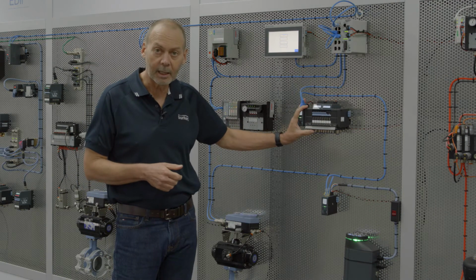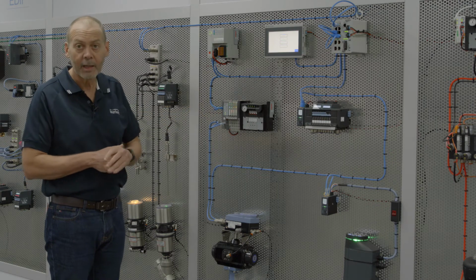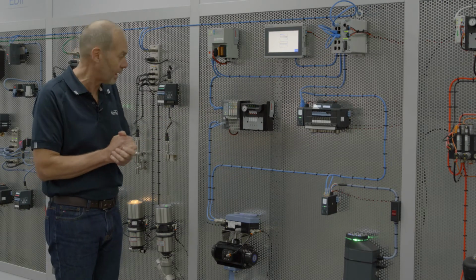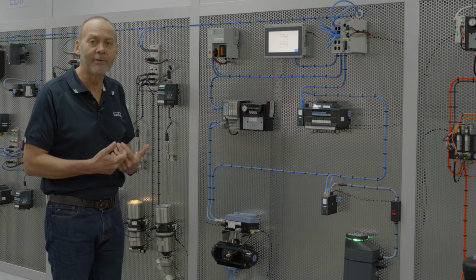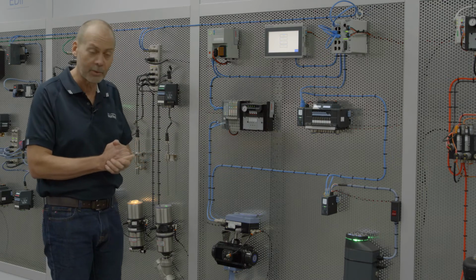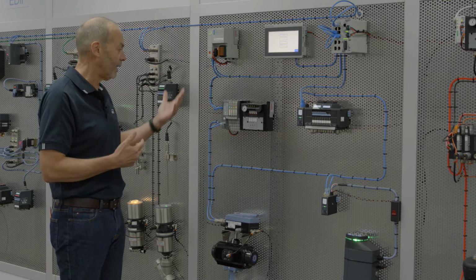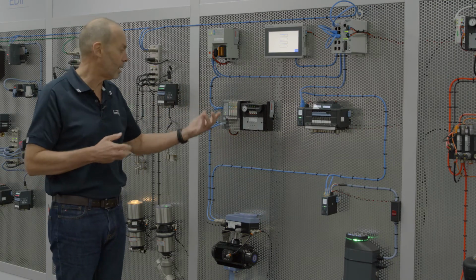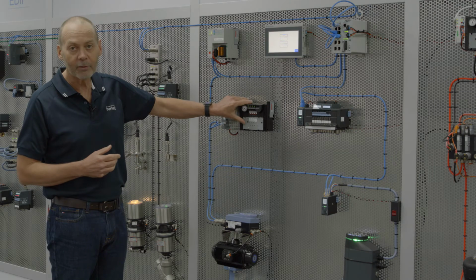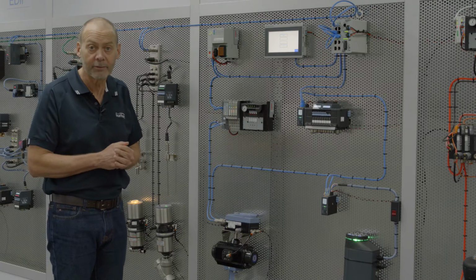One is a pneumatic block manifold, and the other one is the integration that Bürkert has with Rockwell and their Point I/O system. This integration is around 15 years old, and it's still quite current. What it gives you is the capability to have a complete I/O cluster in a remote field situation. In other words, not just having a valve bank where you can have some pneumatic outputs, but actually having a mixture of analogs, digitals, maybe some high-speed counters, temperature sensors, whatever you wish, as well as valve outputs as well. And they can all sit in a simple cluster that can be put into the field.